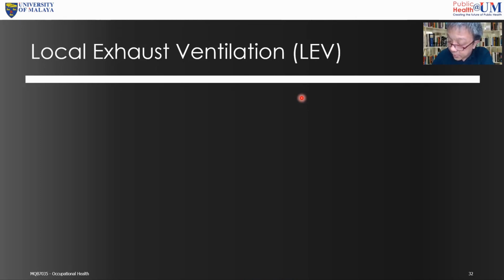Is there fresh air now? It's not fresh air, sir. Okay, so in a split aircon unit, there's no fresh air. The air just circulates within the room and is cooled within the room. So it's just like what you do when you press the circulation button in your car. There's no fresh air coming in, so the air actually goes within the room itself only.